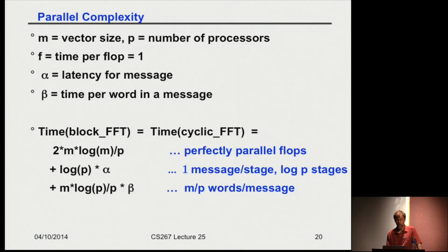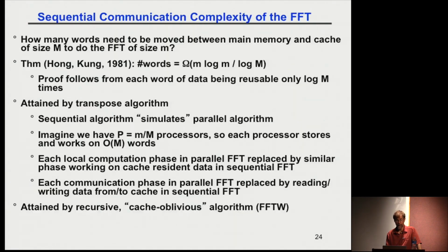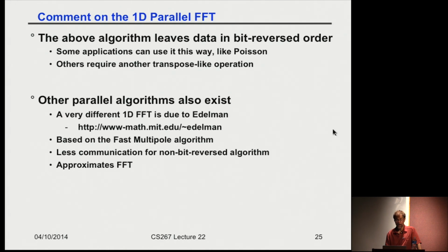So now, what happens when I run the FFT again, where the input is in bit reversed order? That means I'm going to bit reverse it again. So I go from input is regular to output is bit reversed, then input is bit reversed, and what's the output? What happens when I bit reverse twice? It comes back to the original order, right? So the output comes out perfect. I don't have to even think about it. So that's very nice, and it's often that you do FFTs in these pairs, and so everything is just fine.